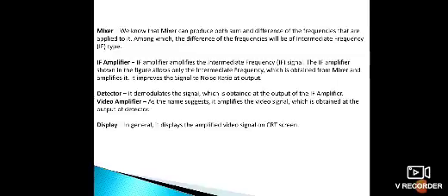Why? Because for processing of the signals, the RF signal is not directly processed. It can be processed only at intermediate frequencies, so we have to convert to IF stages. For that reason we use the IF amplifier in the receiver section, and the main intention of using it is to improve the signal to noise ratio at our output stage.